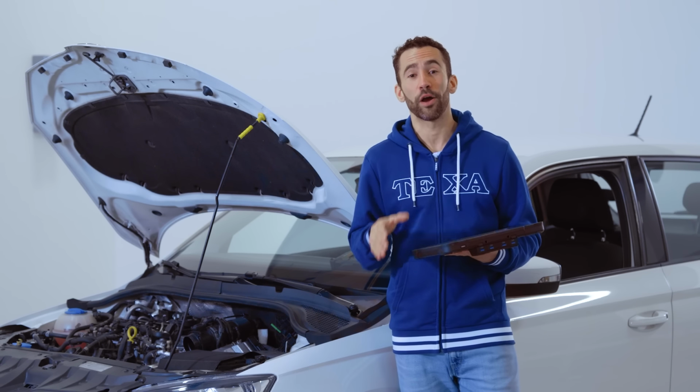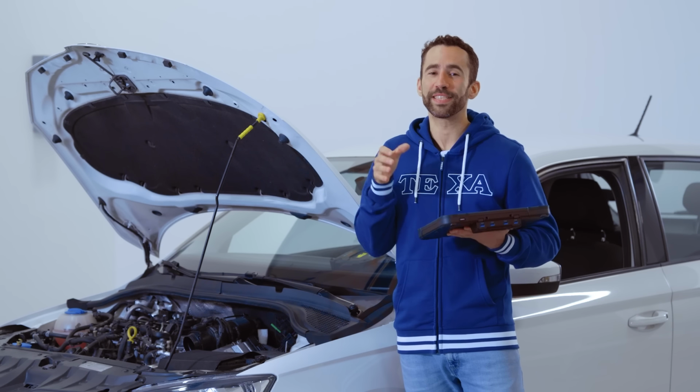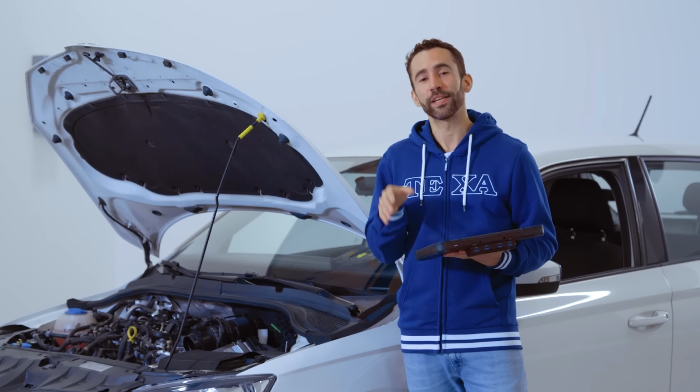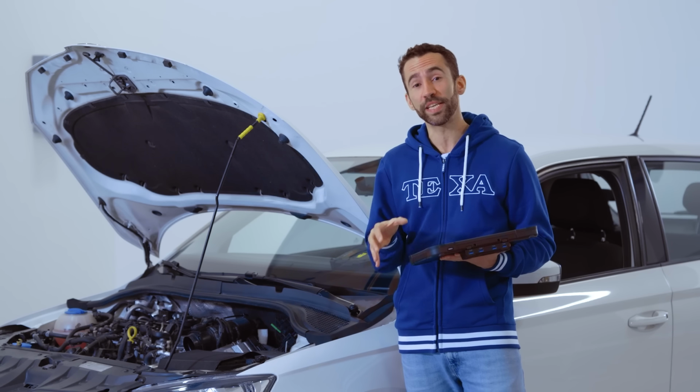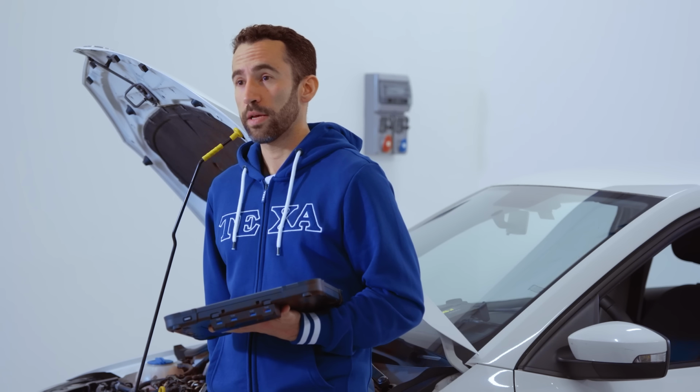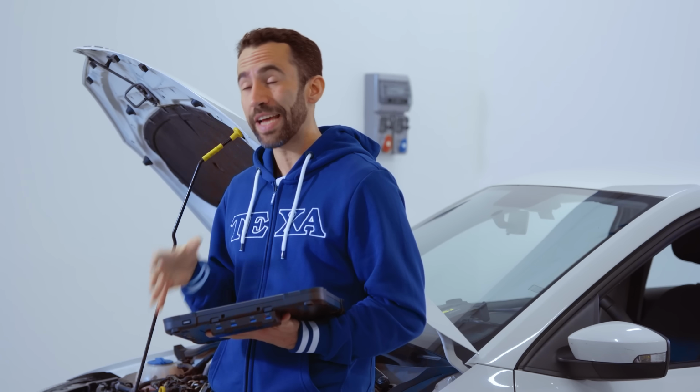After disconnecting all these components, we have identified the problem being in the turbo pressure solenoid position sensor, which has an internal short circuit between the 5-volt positive and ground. And this caused the activation of the control unit outlet protection that shut off the power to the complete line.